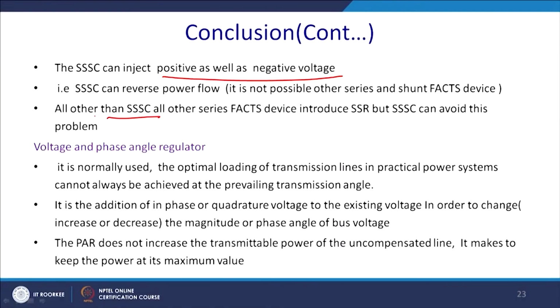All FACTS devices other than SSSC introduce subsynchronous resonance and the problem of subsynchronous oscillation. This problem is not there with SSSC, and thus no damping device is separately required to be placed.